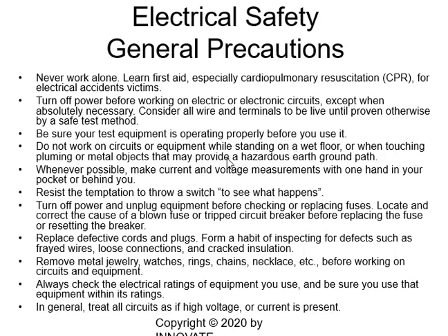Do not work on circuits or equipment while standing on a wet floor or when touching plumbing or metal objects that may provide a hazardous earth-ground path. A wet floor is really very bad. It will reduce your resistance and will be a dangerous path for current and electric shock. Whenever possible, make current and voltage measurements with one hand in your pocket or behind you. This will reduce the flow of current to your body.